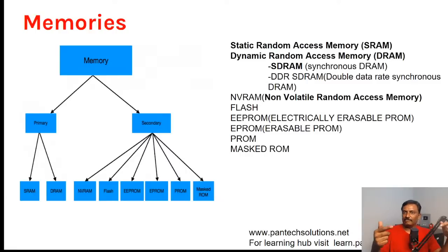In DRAM, you have SDRAM, DDR SDRAM, mobile DDR RAM, and DDR3. All these DDRs stand for double data rate synchronous DRAM. It will be very much faster. Even now, they are not using SDRAM; they are using only DDR3 and DDR2 like that. DDR SDRAM usage is quite low. If you use a mobile device, then they will go for mobile DDR SDRAMs.